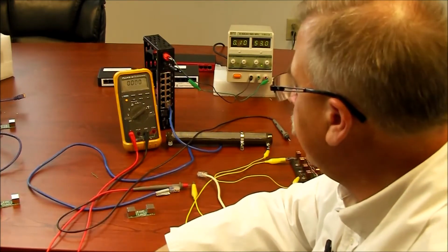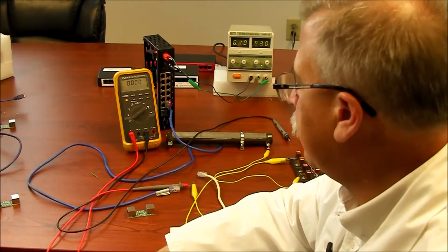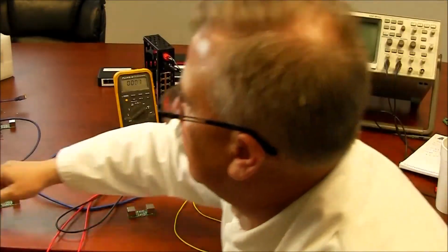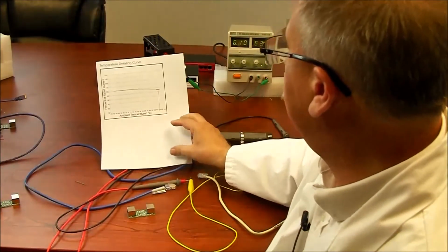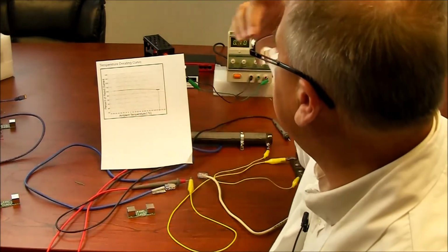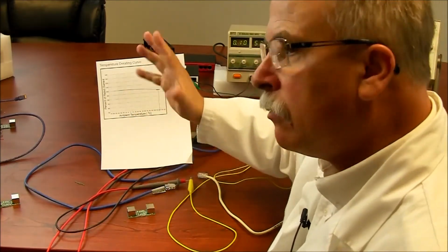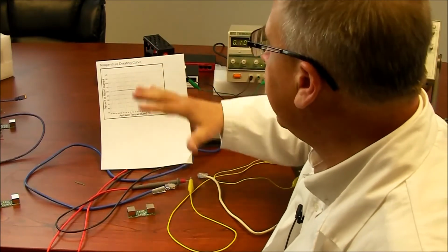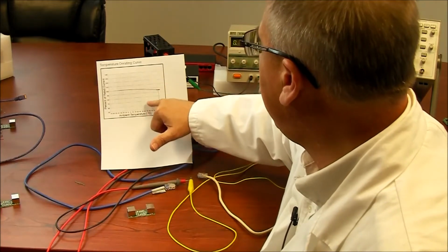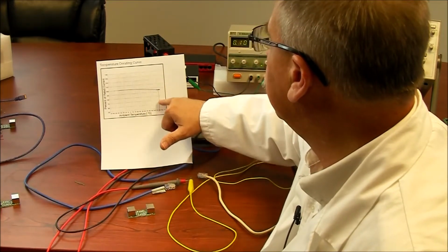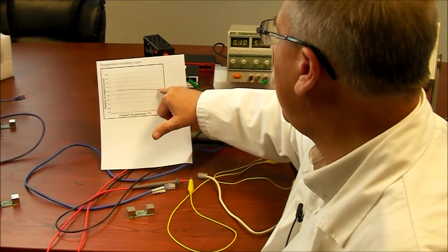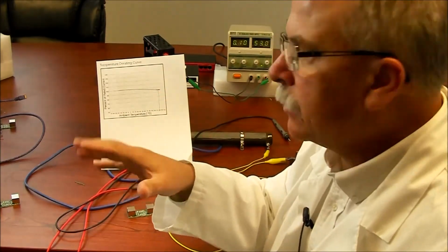So anyhow, that's the end of the video. I enjoyed doing this project. I thought it was going to go a lot quicker because I thought the fuse guys could tell me a little bit more about their fuses. Now, as it turns out, this is their derating curve, and at 125, I thought they might be real temperature sensitive. Nah, it blows at pretty much 100% of its rated current until it gets up here and pretty hot. But even at scorching hot temperatures, which you'll never find, hotter than what it takes to boil water, it's only at 95%. The current has dropped down.